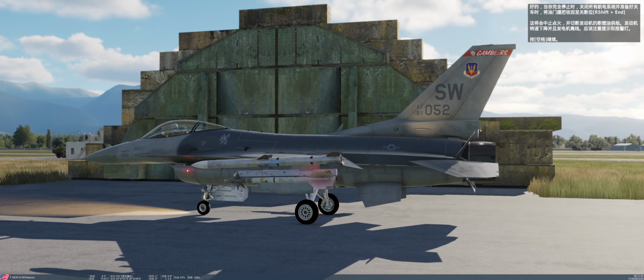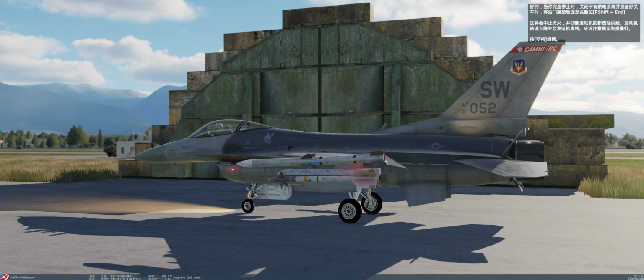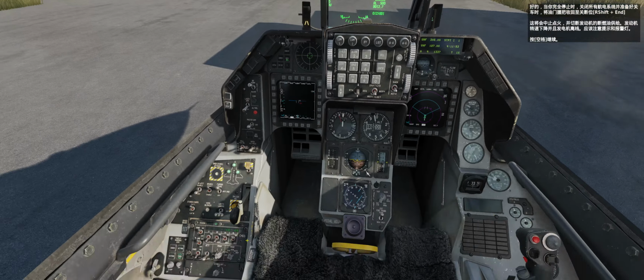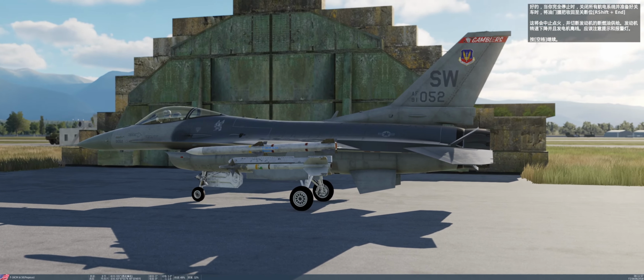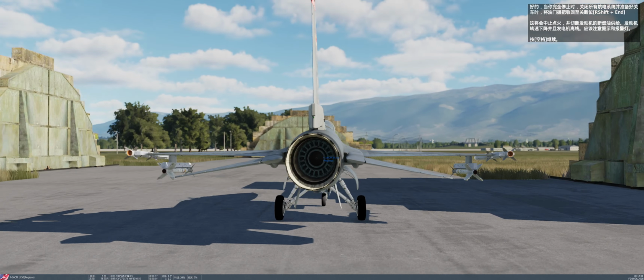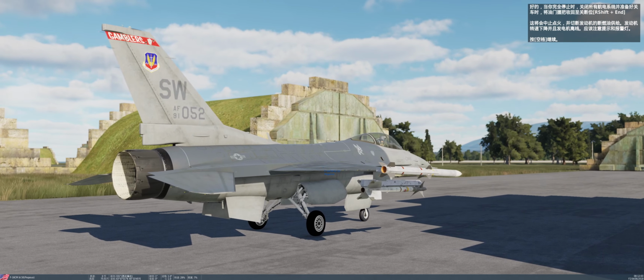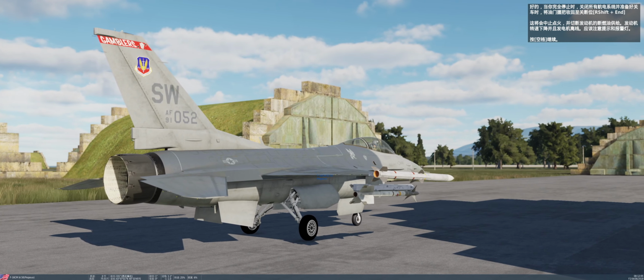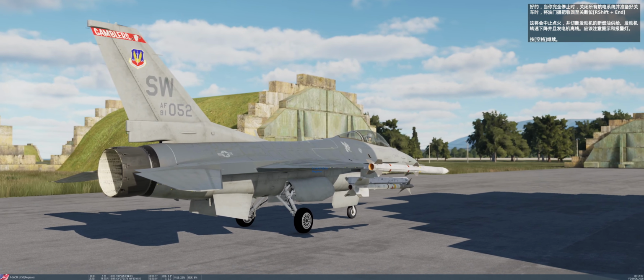Okay, when you have come to a complete stop and have turned all avionics systems off and are ready to shut down, pull the throttle aft past the idle stop. This terminates ignition and shuts off fuel supply to the engine. The engine spools down and the generator drops offline. Caution and warning lights are to be expected. Press spacebar to continue.